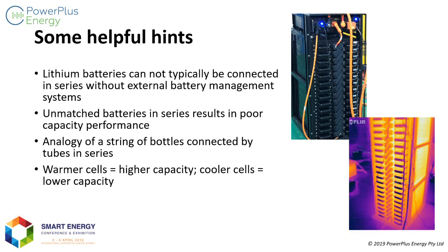So what we've done is put the packs into a much tighter, compact arrangement so that any temperature variations are very limited across the pack, so that the cells don't suffer from poor cell capacity balance from one side of the pack to the other.